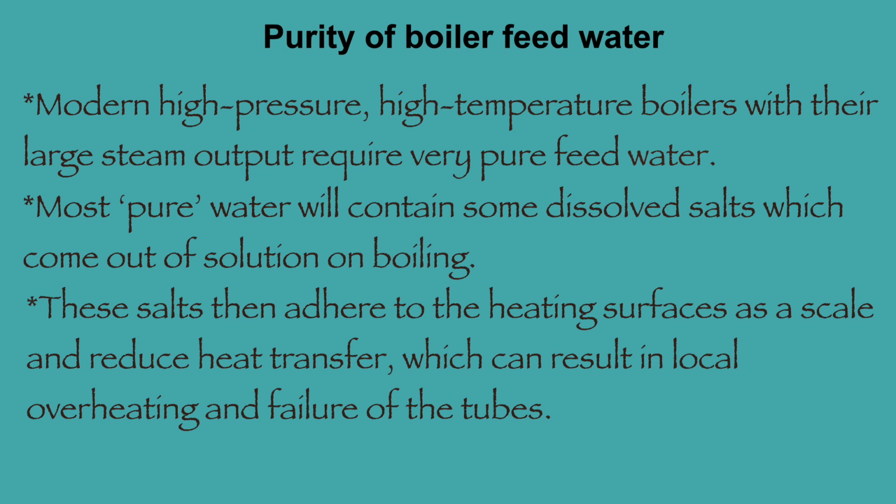Purity of boiler feed water. Modern high pressure, high temperature boilers with their large steam output require very pure feed water. Most pure water will contain some dissolved salts which come out of solution on boiling. These salts then adhere to the heating surfaces as a scale and reduce heat transfer, which can result in local overheating and failure of the tubes.